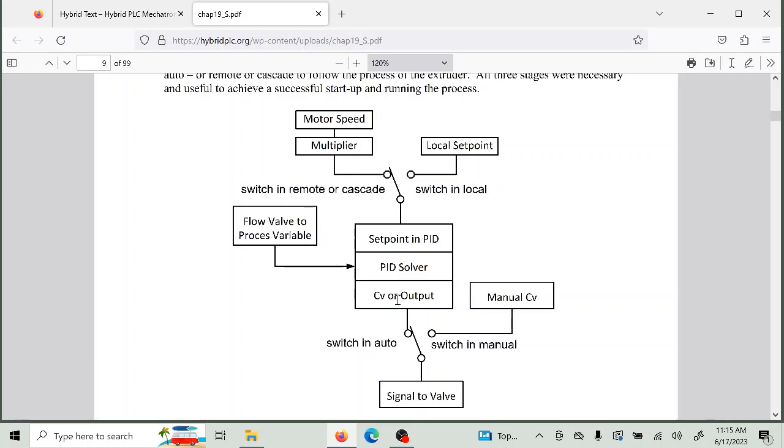Now, auto tune is not available in some of the Allen Bradley units. I don't know if it's available in some of the more expensive units, but it is not available in the units that I had when I was trying to do this. So I had to guess. And I guessed pretty good on the P term, but on the I term, I thought it would be better if I made that TN term big. And I made it as big as I thought it should be.